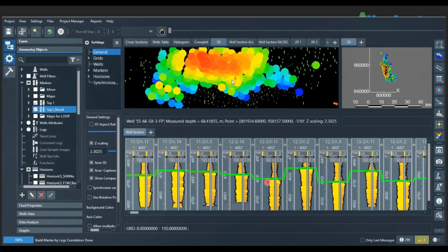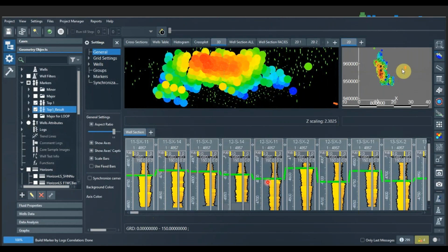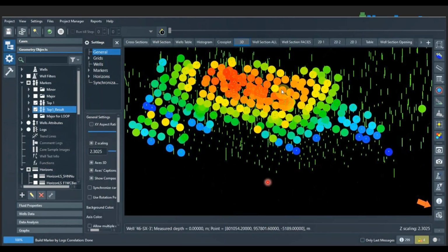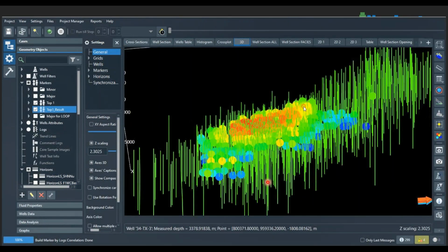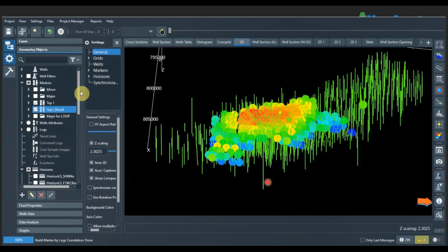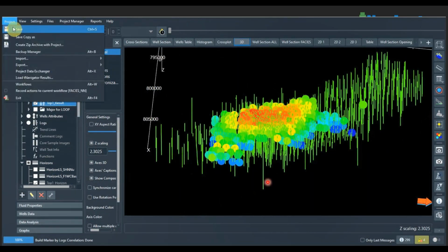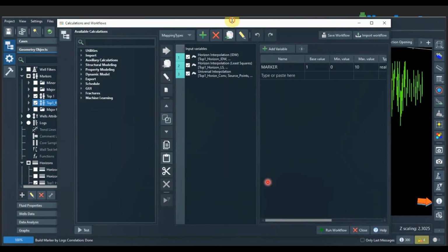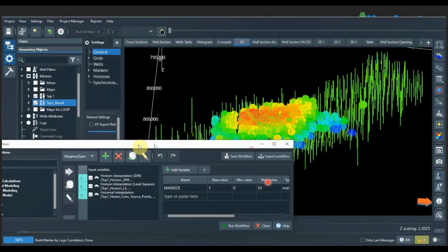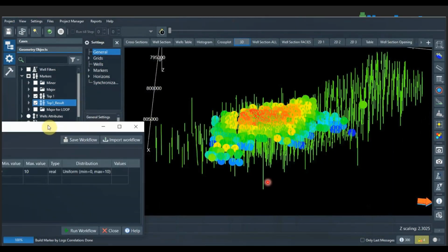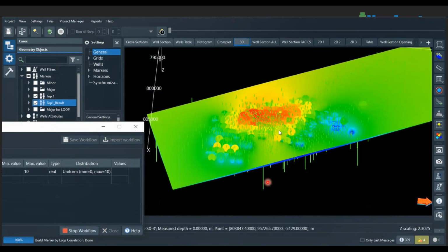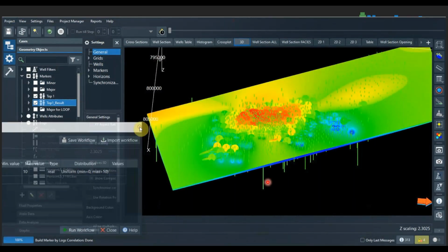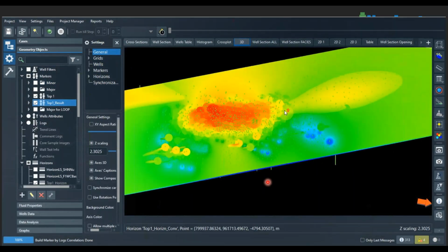And then what you can do next is, of course, start to generate your depth structure, right, based on your well markers loaded. So let's create the depth structure. Of course, you have several choices for the interpolation algorithm that you want to use. For this particular example, I will show you 3 main common algorithms that people typically use for creating depth structure. And I just use it in the workflow, so instead of having to click one by one, I can just do it in one go. So in an instant, I can already have my 3 different depth structures.